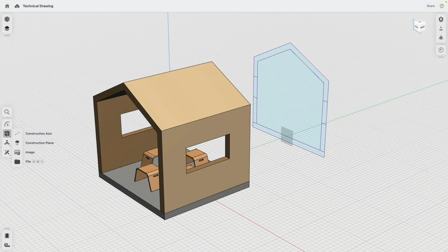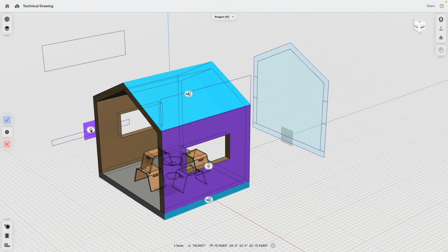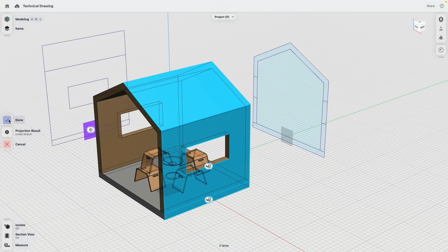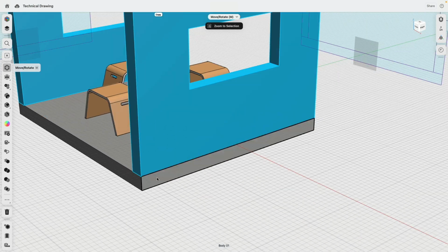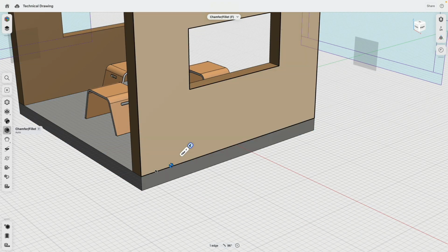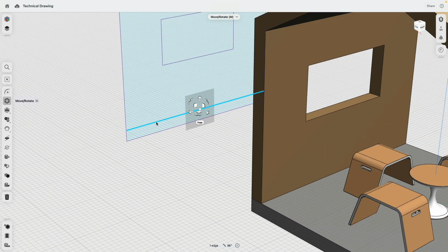Let's do this one more time. We go to add construction plane. I select this one there, back 150 there. I work a little bit sloppy and make a mistake on purpose. We project onto this one, click done, and all looks good. But this body and this body share actually an edge. Or not share, but we have two edges there at the same position. So here we do have actually two lines. If I press delete, there you see, there is still actually the line.